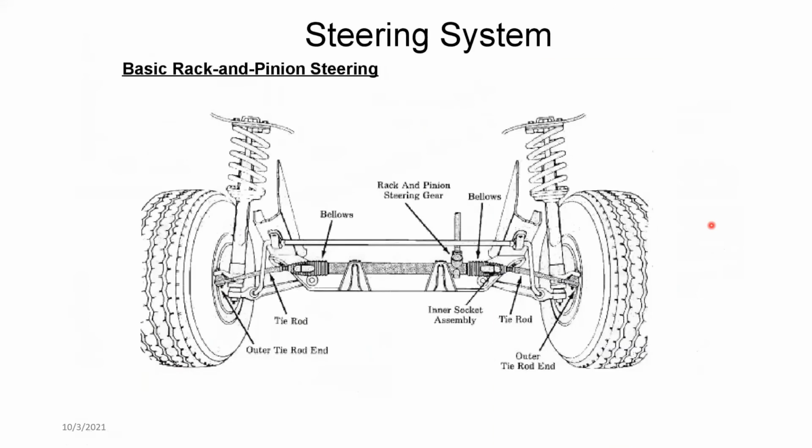So this is the rack and pinion steering, and you can see this now very well. If we come here, you have the front suspension or this hydraulic damper coming up, and it's connecting to the knuckle. This thicker section over here is known as the steering knuckle, right? From the knuckle, there's an extended part which comes and connects with the power steering, or the steering rack in this case.